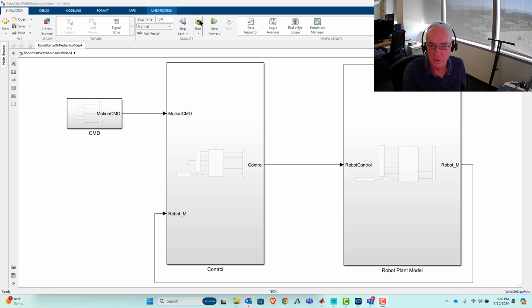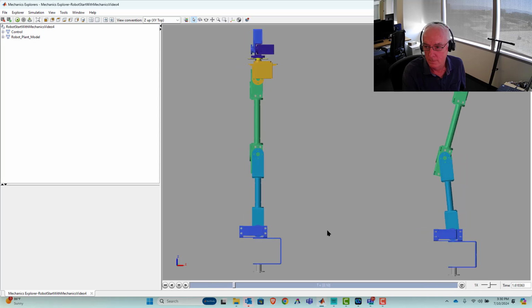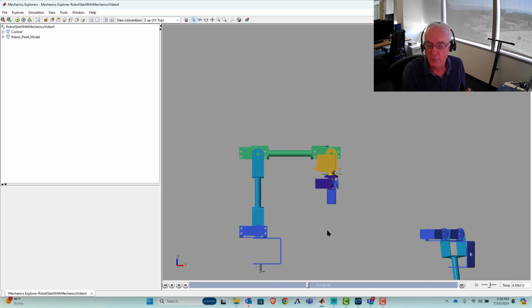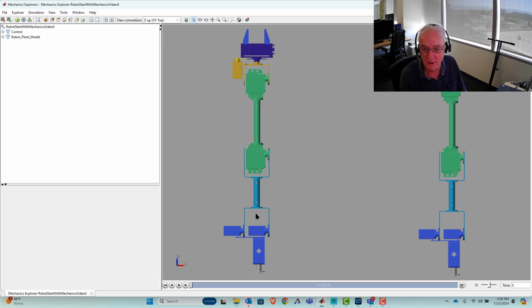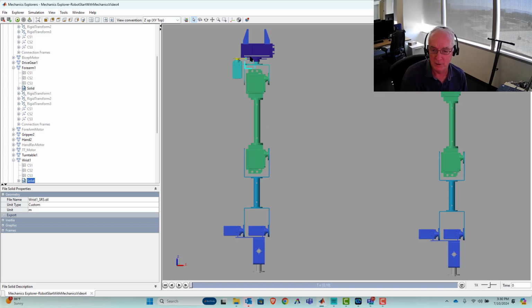So we're starting off exactly where we left off in the previous video, which is that our feed-forward strategy for calculating the torques required to get the movement we want from our prescribed motion robot does not work. It does not work because, if you look at the robot, you can see one, two, and really three inverted pendulums all stacked up on top of each other. It's a substantially unstable mechanical system.